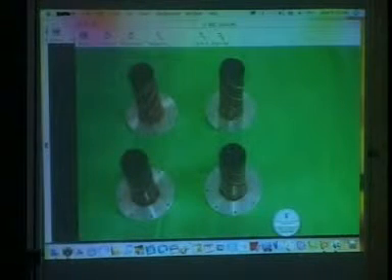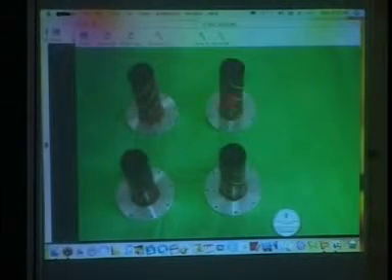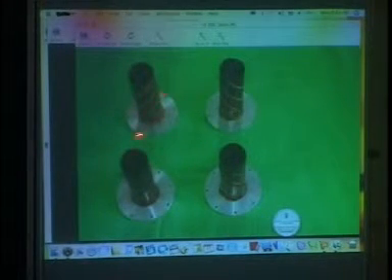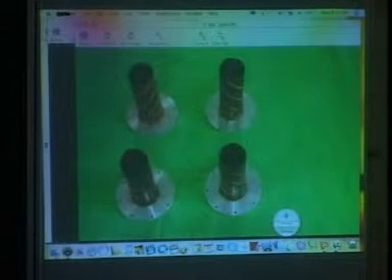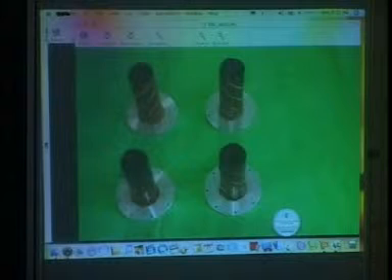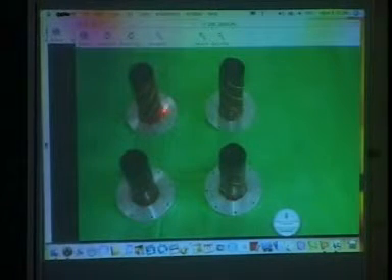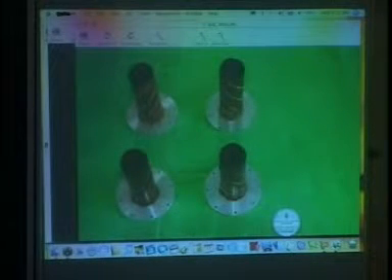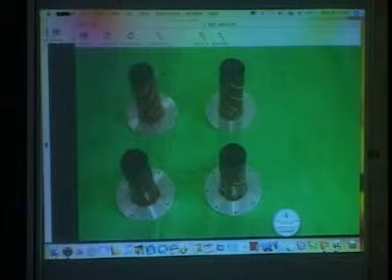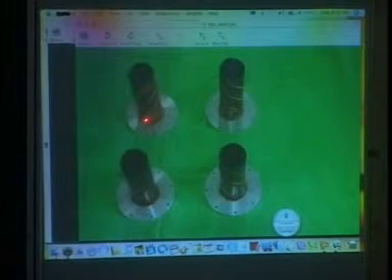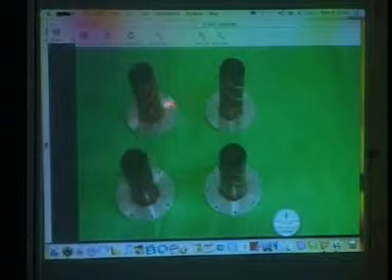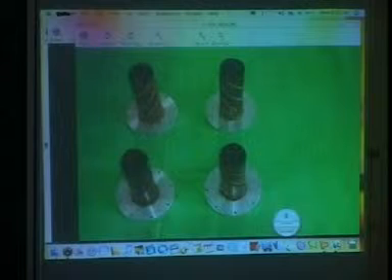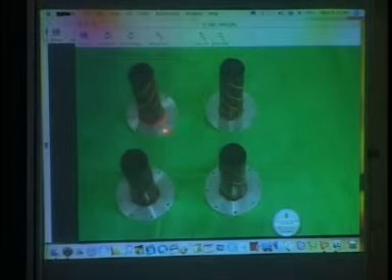On a single PCB you etch as per requirement, then roll it off and bond it, and then hold it on a small circular aluminum plate, which can have a small extension with which you can nicely hold it. Then this is the epoxy, H54 epoxy made by a specific company called Epotek, and this is a NASA-qualified material. And this is the feed network, which gives the required amplitude and phase for all the elements, and finally there is a connector at the base with which you can take the signal out.